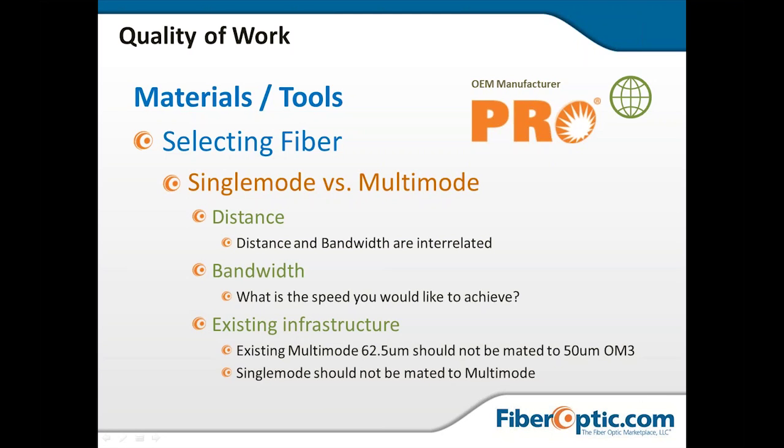As an example, let's say we had a 2-kilometer fiber that we were running out to a security camera at the end of a mine, a coal mine entrance or something along those lines. If we only have a send and receive, which is 2 transmitters and a transmitter and receiver, and then we had 2 kilometers of fiber, the extra cost of the multi-mode fiber at that length actually outpriced the benefit of the electronics. So it actually made sense when we would design it for people, and we were estimating the project, we actually flipped it over to be single mode.